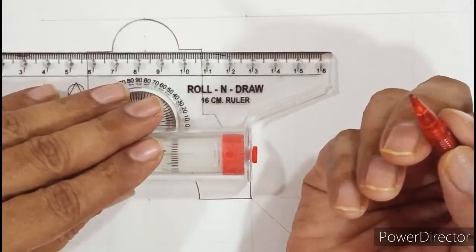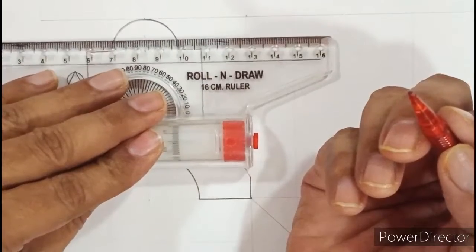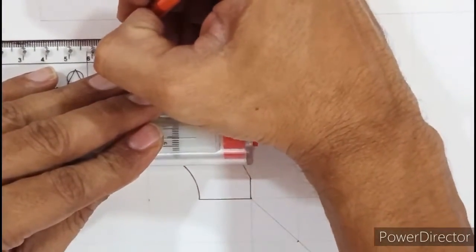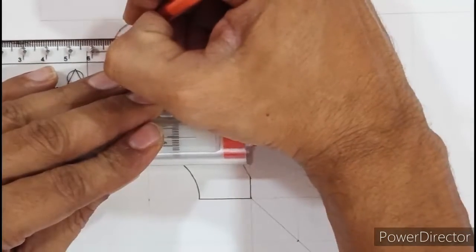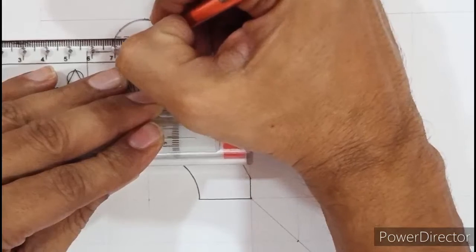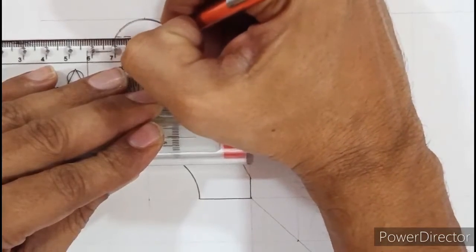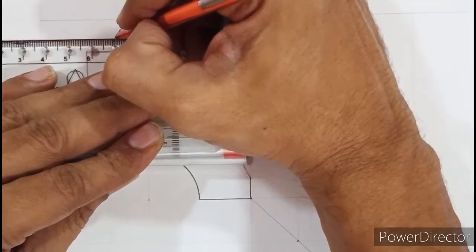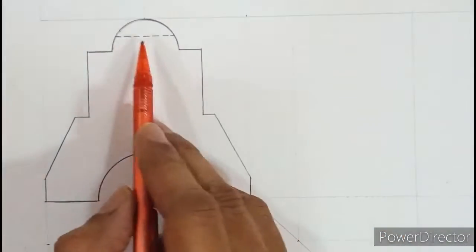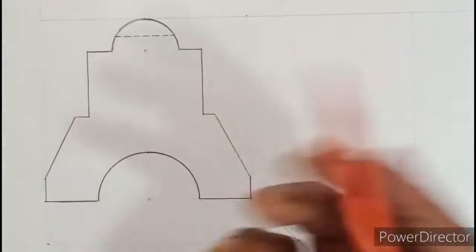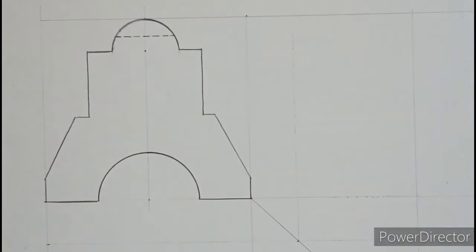and I draw a neat hidden line. All of you remember the nature of a hidden line, right? It should be double traced. Darkness should be same as the object line. Length should be more, gap should be less. And it should compulsorily touch the ends of the object line. So that is how a hidden line is drawn. This hidden surface implies the arc of the sector which is behind.